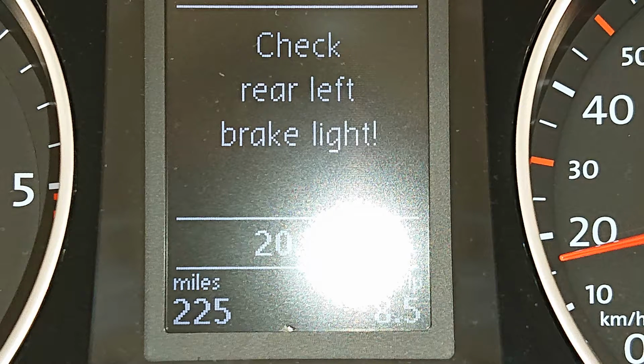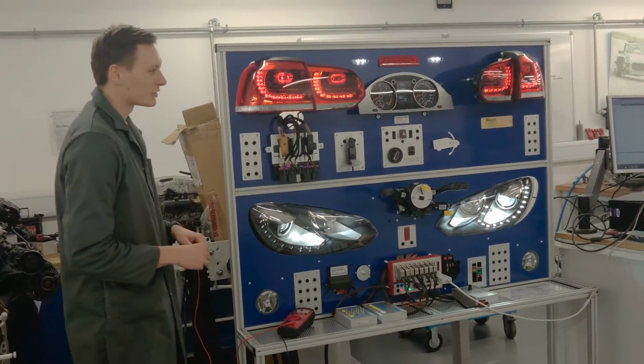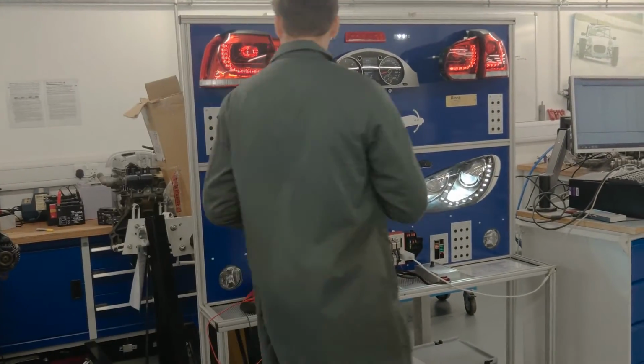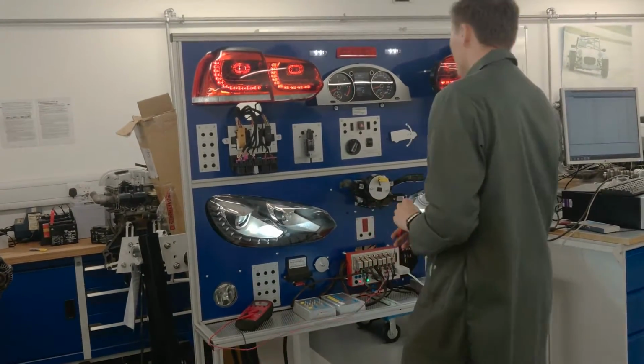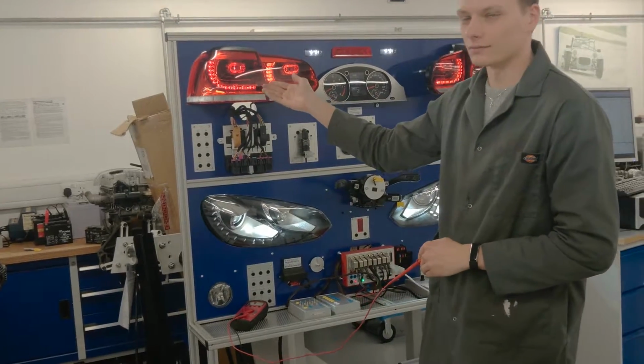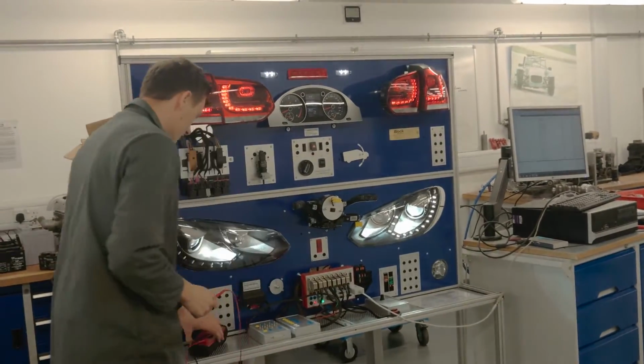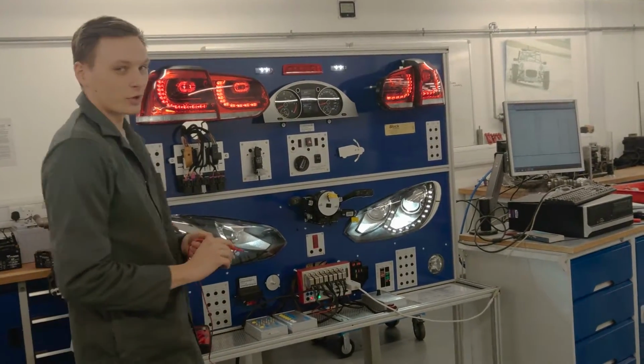The CAN bus light unit tests the circuit with 3 energy pulses. So the unit found there is a fault in the circuit and put up the message on the MFD. Now let's say I presumably fixed the wire on this testing rig, and let's test it if it works. Visually you can already tell it's working, but let's just make sure with the multimeter it works properly.